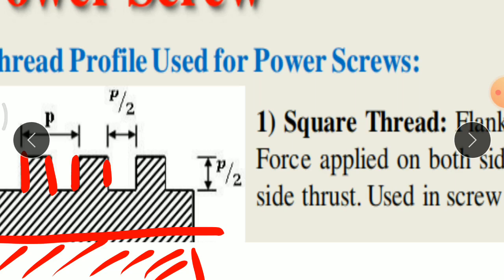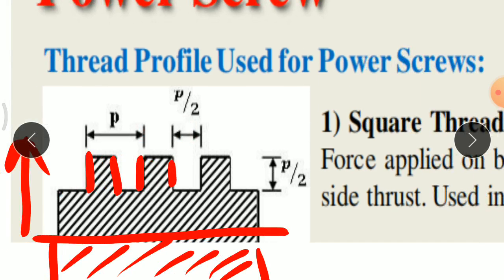And the last disadvantage, or we can call it a limitation of the screw thread, is that this thread cannot be used conveniently with a split nut because wear compensation is not possible, and engagement and disengagement is difficult, as the thickness of the profile is large and it is at 90 degrees. So engagement and disengagement is quite difficult when we assemble it.